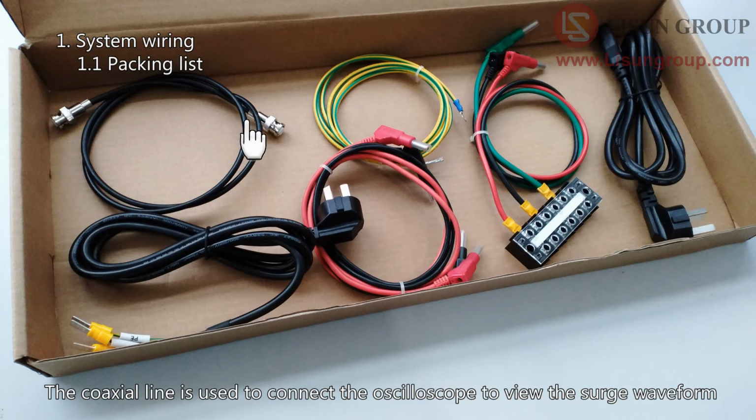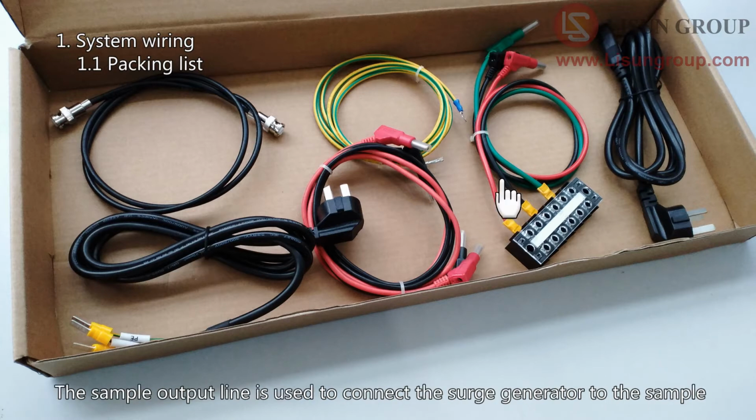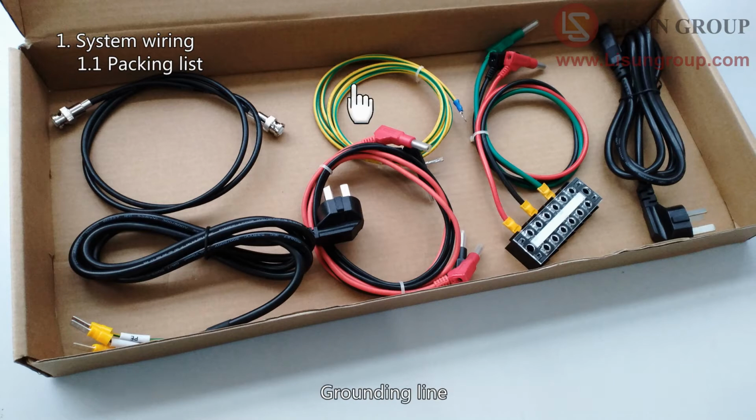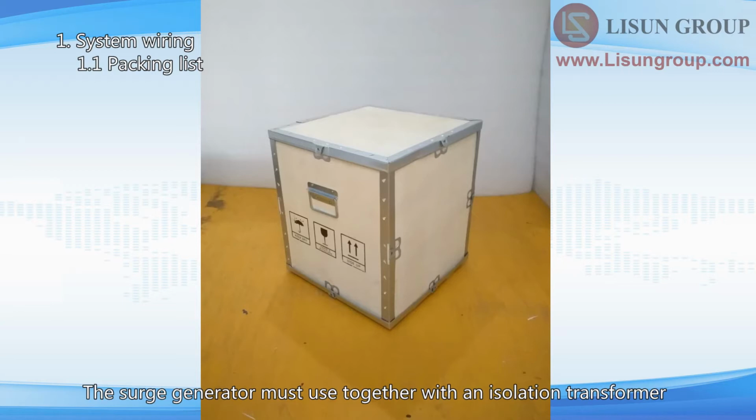The coaxial line is used to connect the oscilloscope to view the surge waveform. The sample input line is used to connect the isolation transformer to the surge generator. The sample output line is used to connect the surge generator to the sample. Grounding line. Power cord. The surge generator must be used together with an isolation transformer.